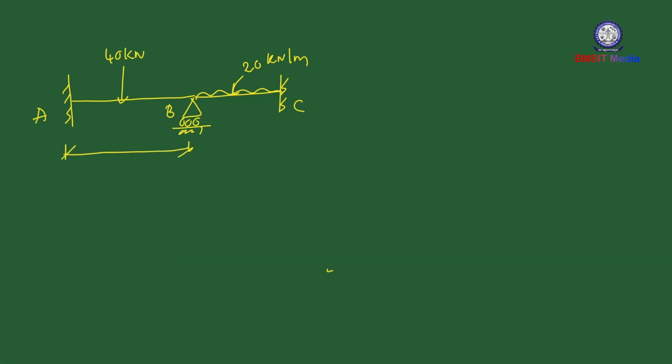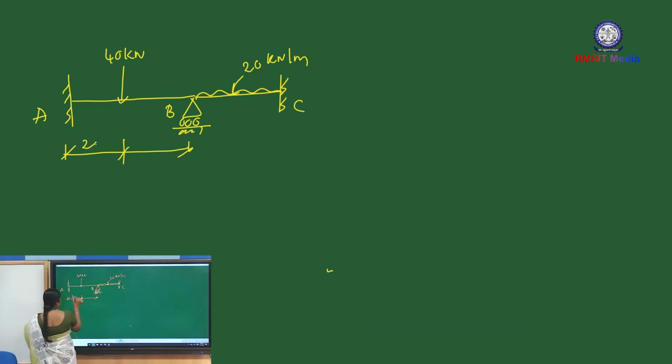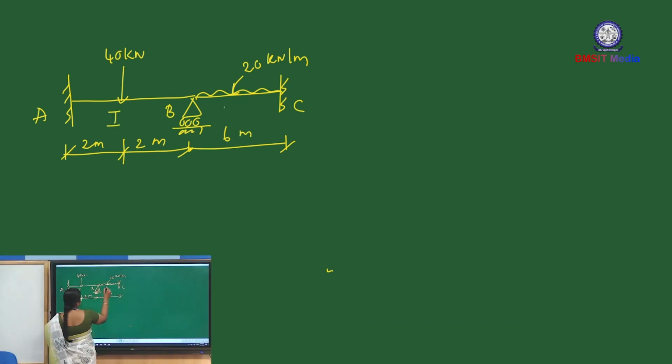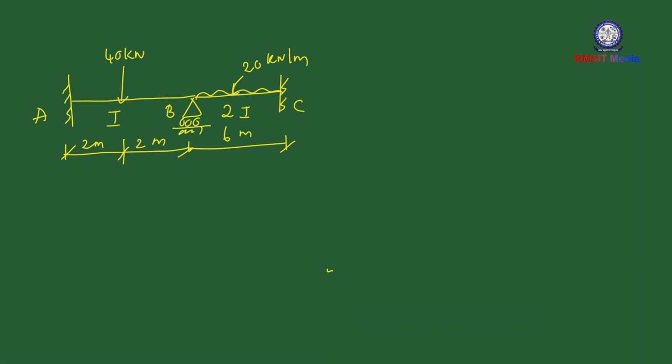The span lengths are 2 meter and 6 meter. The moment of inertia is I, then here 2I. So this is the given beam. We have to draw the shear force and bending moment diagrams using the slope deflection method.